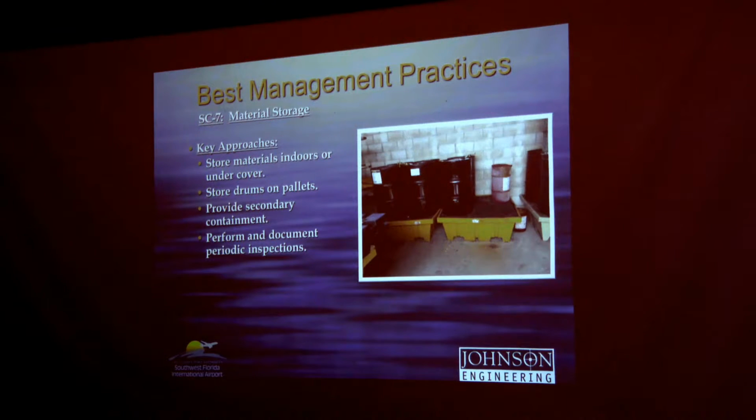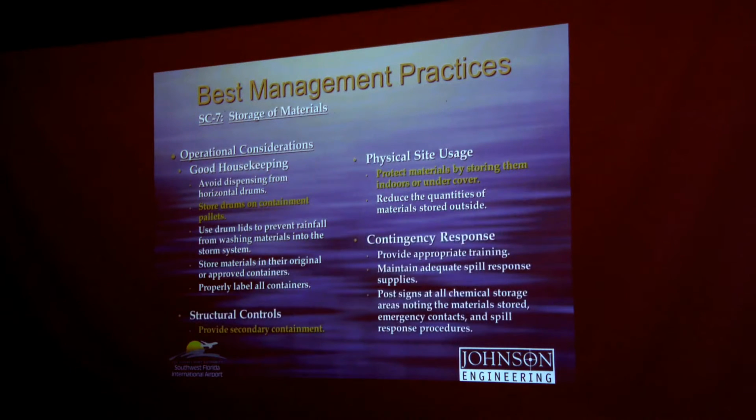SC7, material storage. Key approaches include storing materials indoors or undercover, storing drums on pallets and providing secondary containment, and performing and documenting periodic inspections. Additional operational considerations include avoiding dispensing from horizontal drums. During our inspection, we didn't see any horizontal drums used here on site, and hopefully you guys keep it that way.